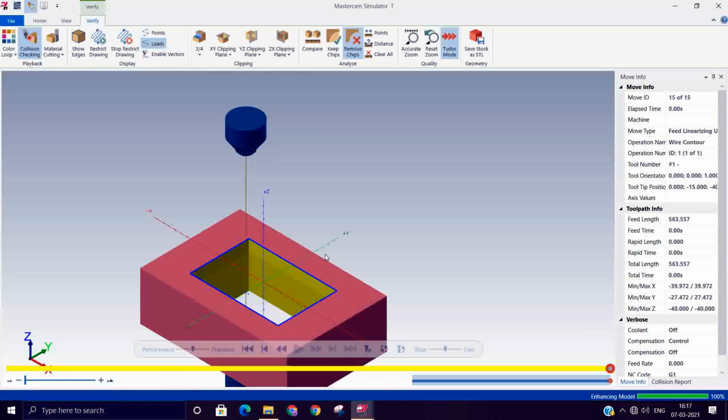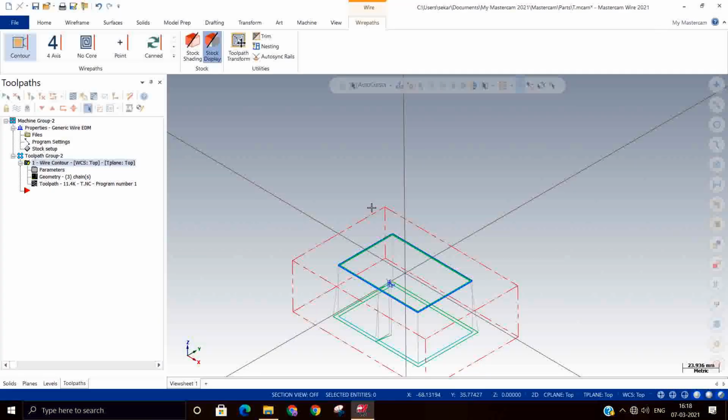You can still explore all the other options. In Fanuc, this taper T is accepted in all Fanuc controllers, but in some machines, in the place of T, A is accepted. So this is customization work, post processor customization work. If you want, we will make it and give it to you based on your requirement. Then we can customize your post processor to suit your machine. That we will make and give to you. Thank you.